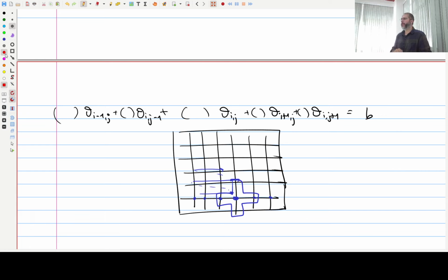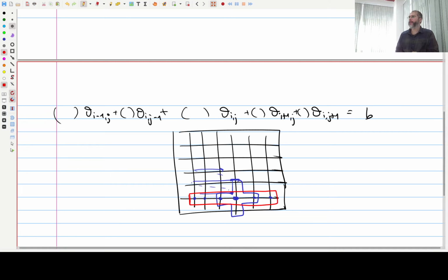And that is what we do here. Rather than using a completely iterative method, we sort of reduce the matrix to a TDMA, a tridiagonal matrix, and then we can apply the TDMA algorithm, because that is very efficient. So what I do is, rather than calculating point by point, I say that I pick this whole line and I'll be solving the whole line together, just one line, not the whole matrix of points, just one line.